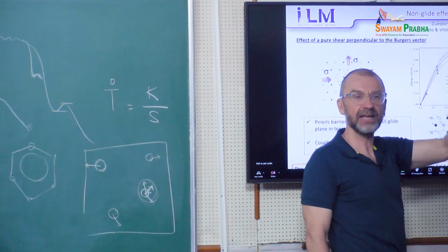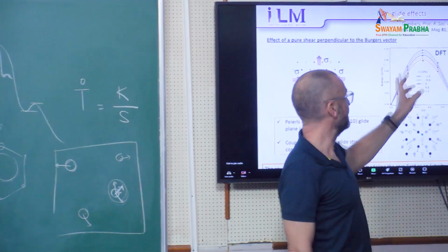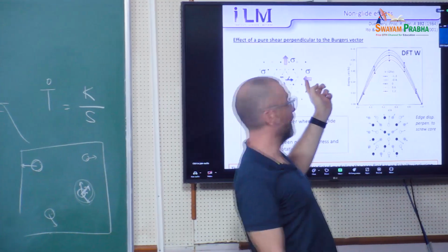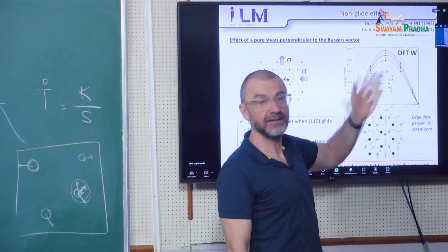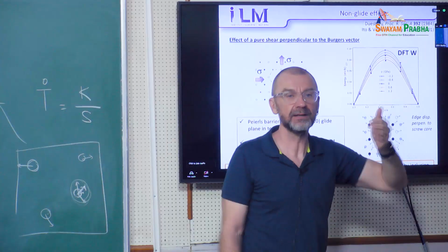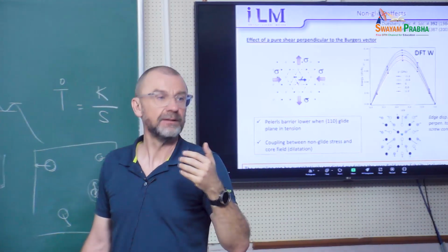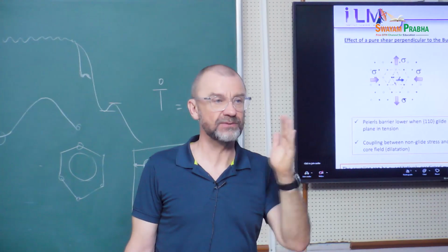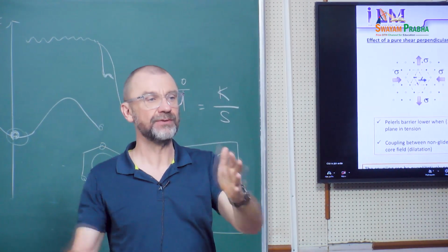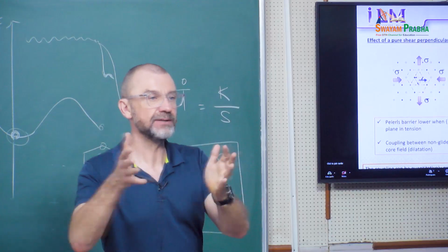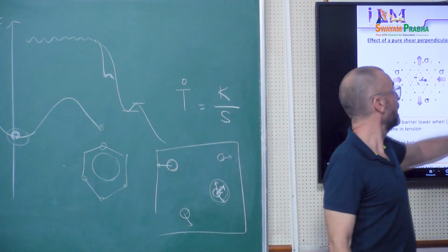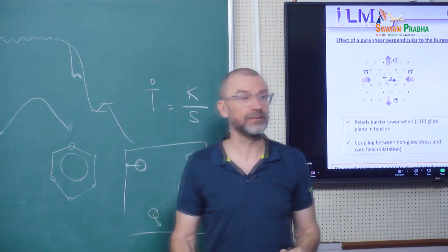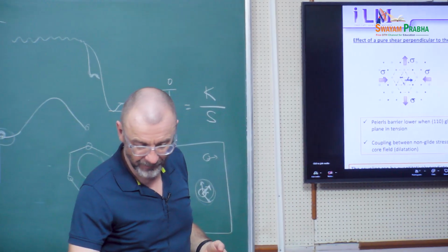I know that if I have an eigenstrain tensor and then I apply a stress tensor on top of it, then the bias on the energy will be the stress tensor double contracted with the difference in eigenstrains between the initial and the configuration where I am, right? So I can rewrite the enthalpy.